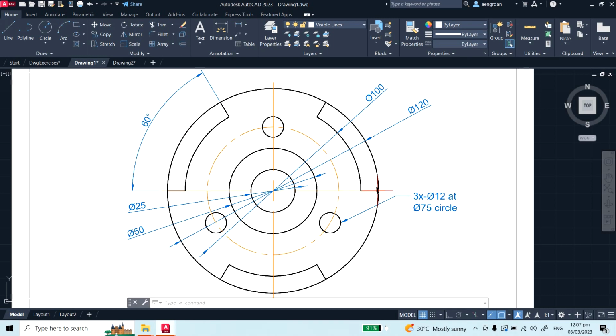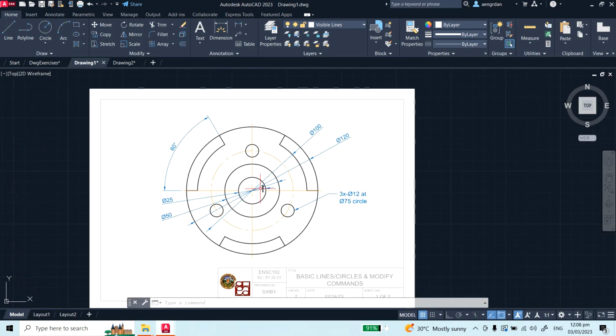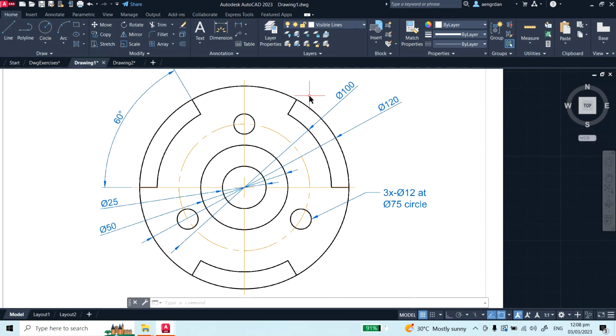If we construct a line here, and then we array it, even along this 360 degrees angle, then we can actually do these drawings. Okay, so another thing to point out is that we could do mirror, because this is also symmetrical, but there are a lot of objects to be drawn first, so that's why the best option here is the polar array.